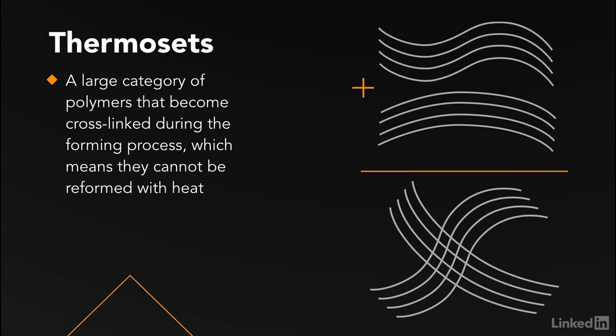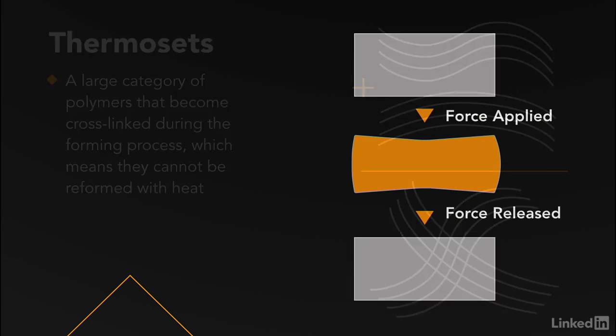Thermosets are the other main category of polymers, which have extra toughness due to the fact that they go through a chemical reaction called cross-linking, where it cures until its final structure. The change creates strong bonds that don't melt. Remember our egg example? They're usually very heat resistant, though at a certain limit they start to degrade instead of melting. Melamine and polyester resins are common thermosets used for sheet applications like counter surfaces. They hold up for a very long time.